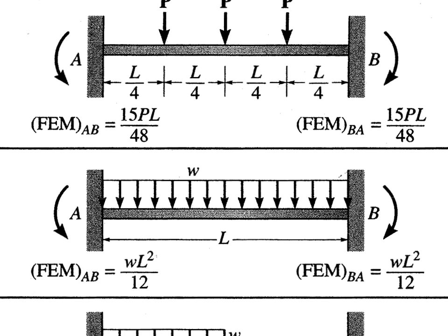So a distributed load is something like this. Conan, do us a favor. Lay it out on the table. Okay. Take a look at that. Go ahead, lay it down. So Nick right now is acting as a distributed load on about two-thirds of the table. His weight is not acting in the middle, even though in diagrams you always draw it from the middle down. Whenever we do free-body diagrams, the weight is from the middle. So I would say there's a heavy distributed load in the middle of your body, a little bit lighter here, and very little distributed load here, whereas this end of the table does nothing. So a distributed load